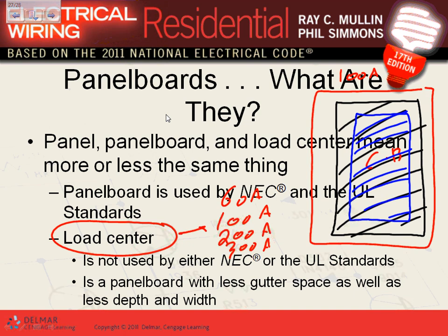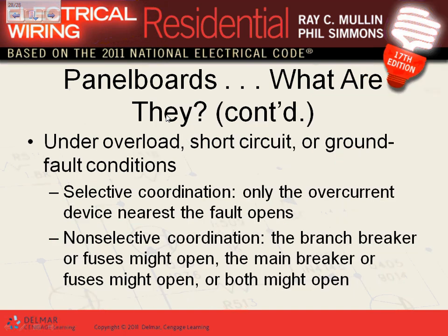So when you think load centers, think residential, very light commercial. When you think panel boards, think commercial and industrial. Does that make sense? The project that you guys are doing, this is called load centers. All the stuff that you size with Chad, those are load centers. That's it in terms of load centers.